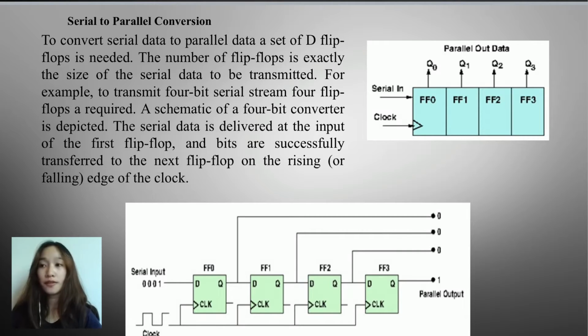Once all the outputs are filled, the converter releases all the bits at once. For this process to happen, the converter is disabled by means of one or more control lines during the transfer process, and enabled once all the bits are at the output bus. This is summarized by stating that the conversion is carried out in 3 stages.